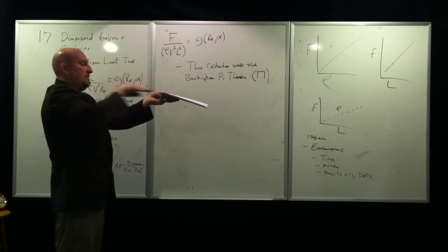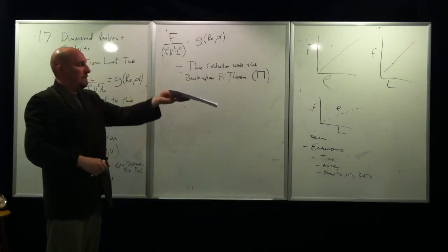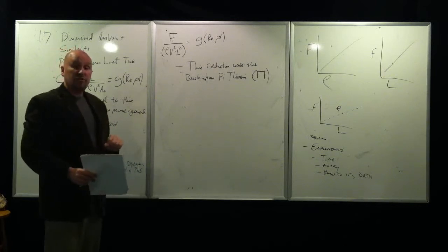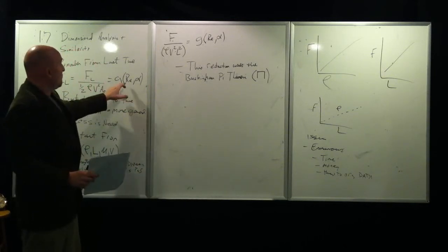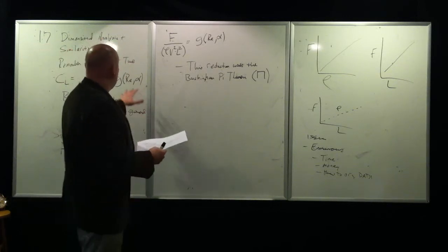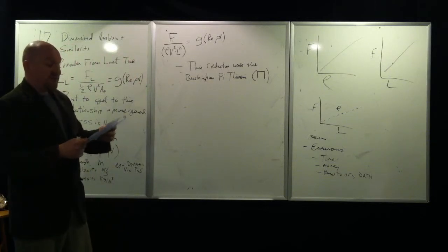So the flow is going in completely parallel with the ground. Angle of attack can be varied, and again your coefficient of lift will change, and it will change generally with Reynolds number. Now, whether it's highly sensitive or not sensitive is another exploration that will need to be investigated.